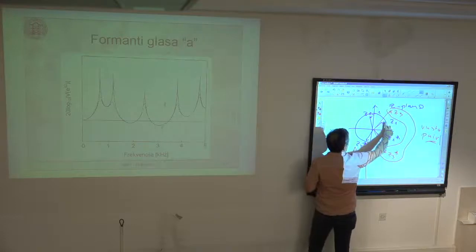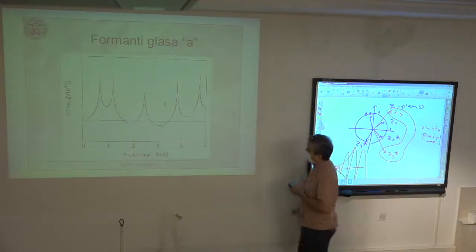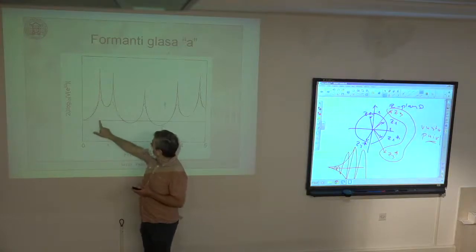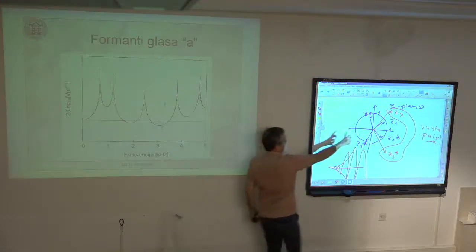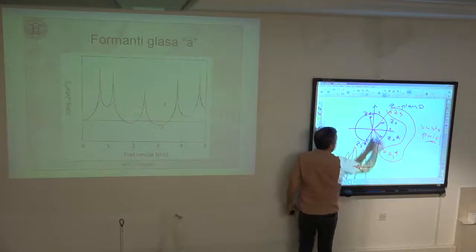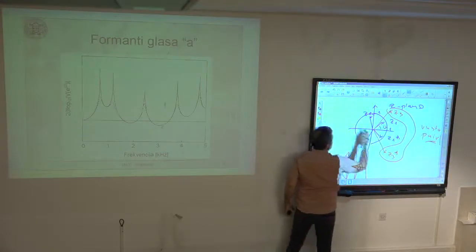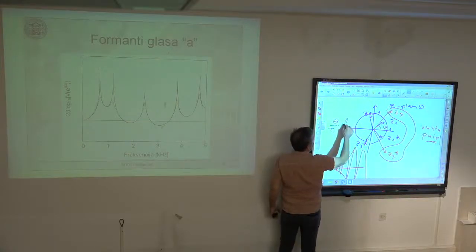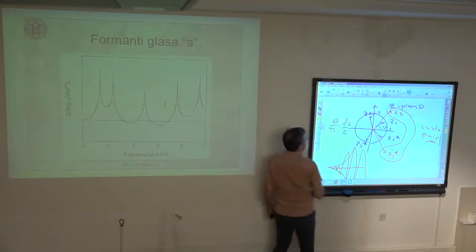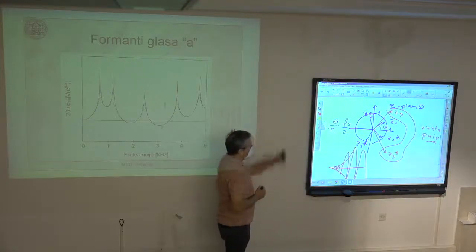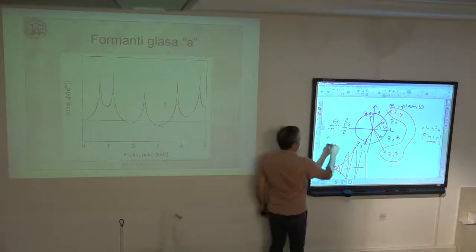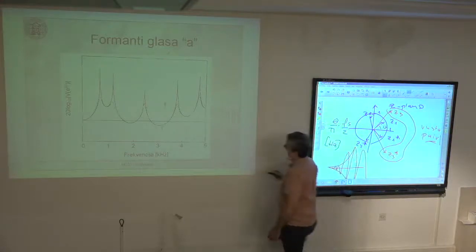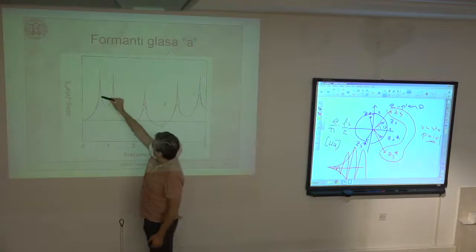So this Z1 and Z1 conjugate complex is the first formant characteristic. I simply take the angle of this first root pair, this angle theta, and if I divide this angle by pi, and multiply it with half of the sampling rate, fs over 2, I will get the frequency in hertz where this pair of poles would cause this kind of amplification.